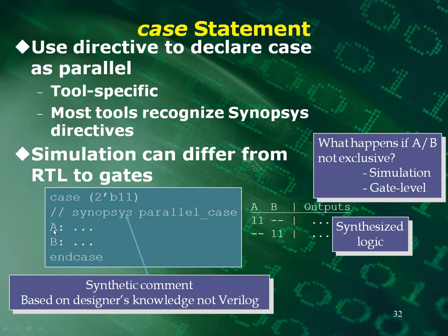Are these compiler directives? Yes, these are compiler directives, synthesis directives. Are they always in comments? No, these are special things that some vendors have come up with, embedded in comments. It's not part of the Verilog language. Synopsys started doing this, and a lot of people followed after them. So it's vendor specific to the tool.